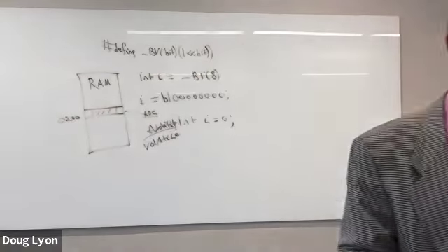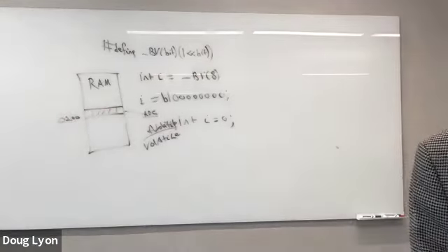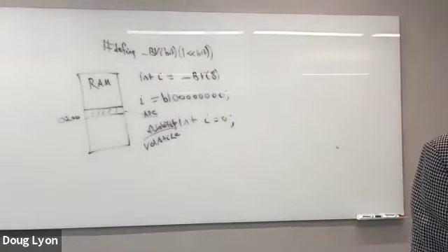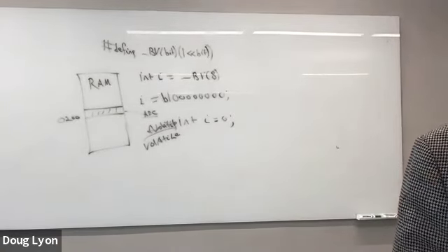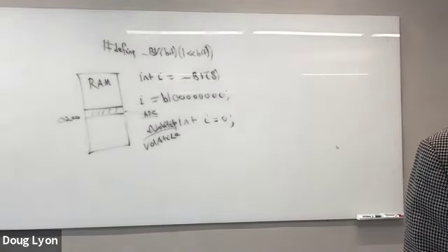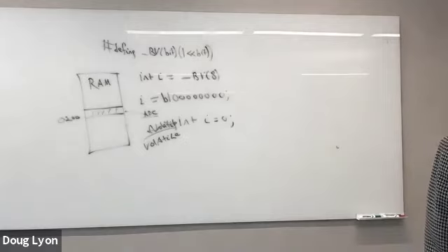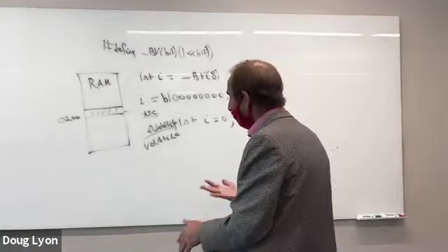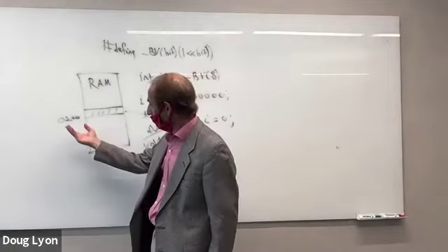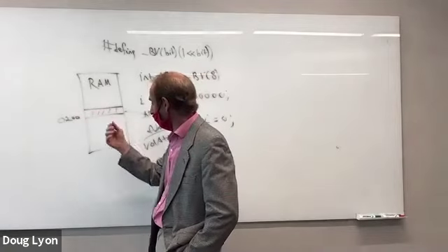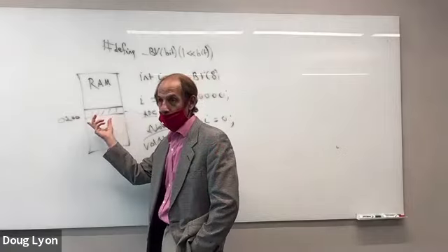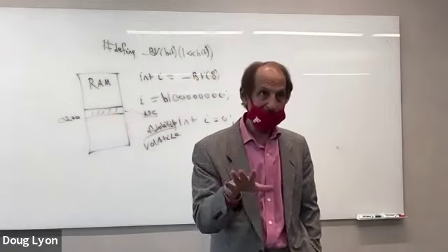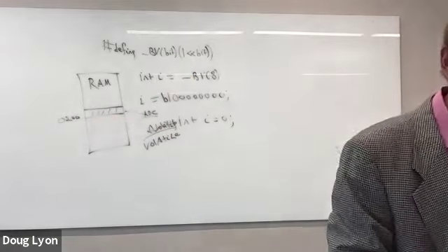If that value comes in and gets changed without the compiler and the runtime knowing about it, then essentially the analog to digital converter is being invoked as a side effect. It's changing because it's actually able to get new data in, and it memory maps that data. And what you want to do is just read the value at that memory location, and the analog to digital converter will handle all of the details of getting that data into that memory location.